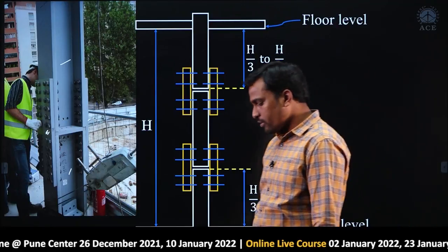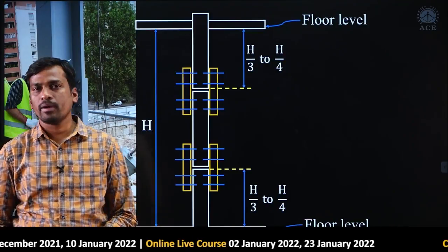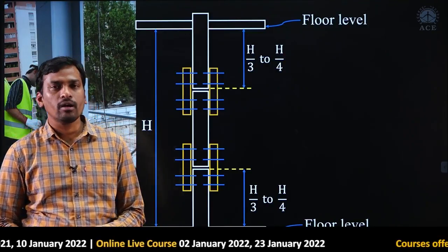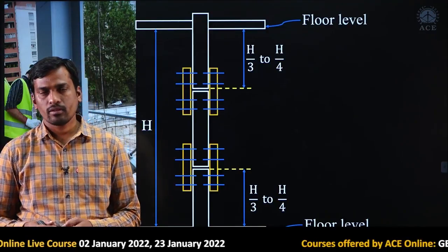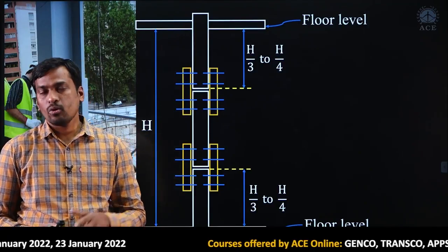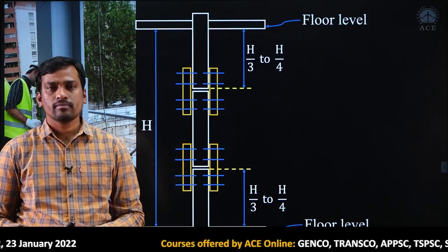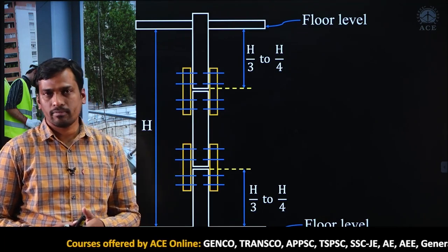Students, where shear force is, where bending moment is maximum, their bending stresses will develop, right? Then there is more possibility of failure. Where stress is there, don't provide the joint there. Where bending moment is less, there we have to provide the joint, just for safety.